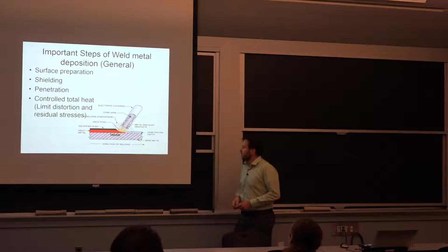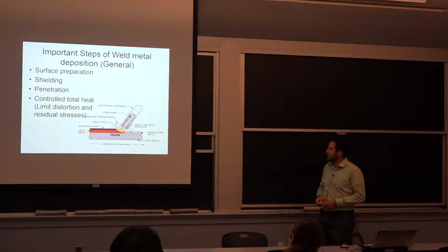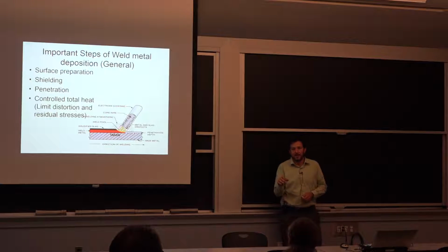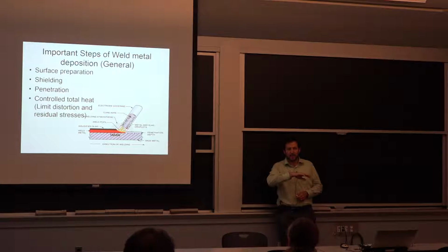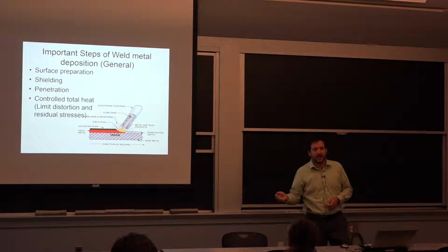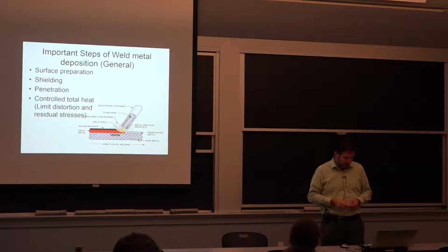So in the most basic process, we use a shielded electrode that also melts and forms that slag on the surface. After the welding is done, it looks really bad because you have that slag that is covering the actual metal. So people have to hammer it down or brush it down to actually have the bare metal and then do the painting.